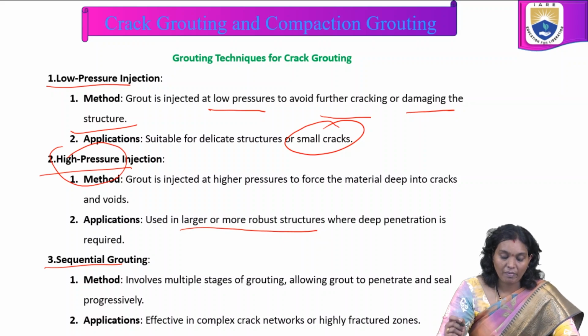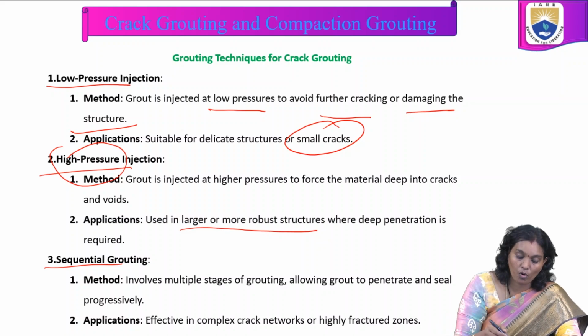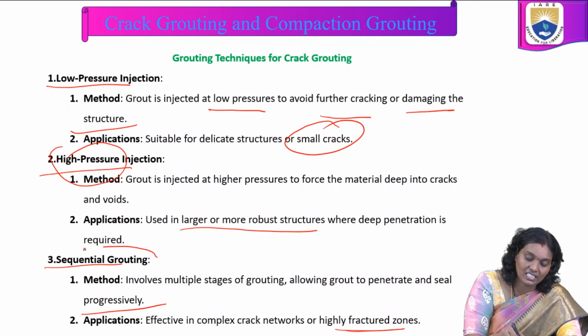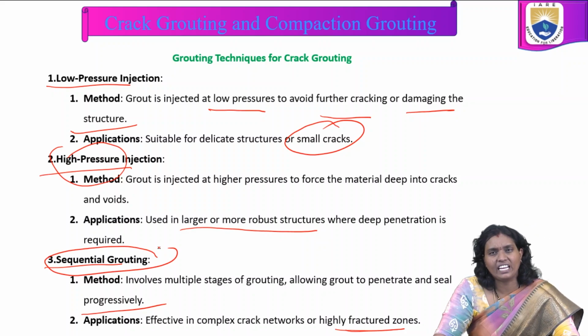This method involves multiple stages of grouting, allowing the grout to penetrate and seal progressively. It is effective in complex crack networks or highly fractured zones, where we choose this grouting technique, that is sequential grouting.